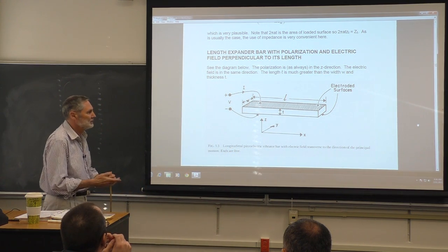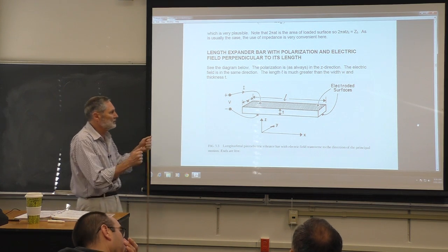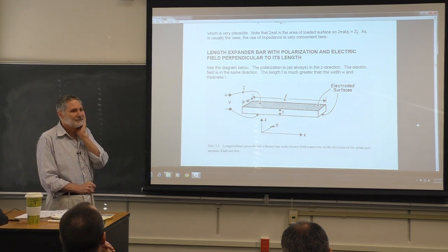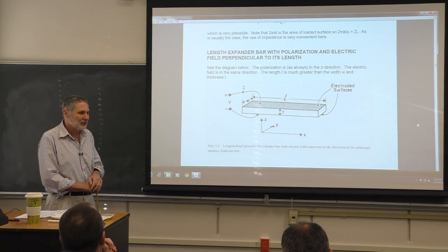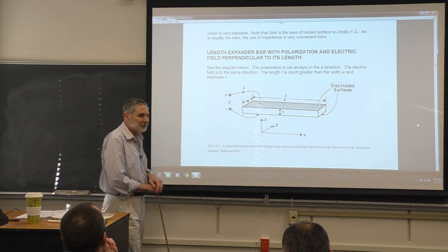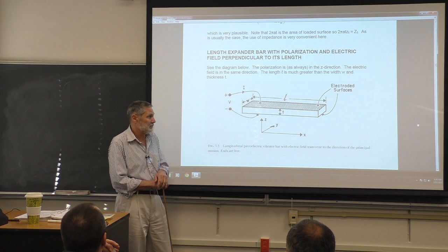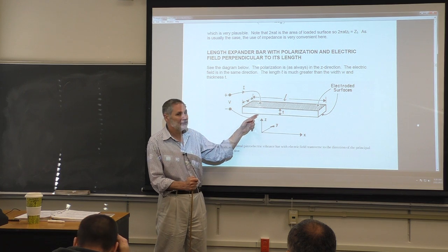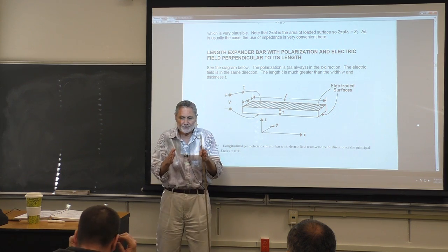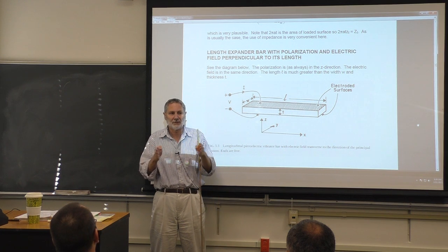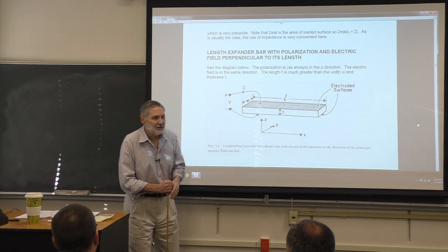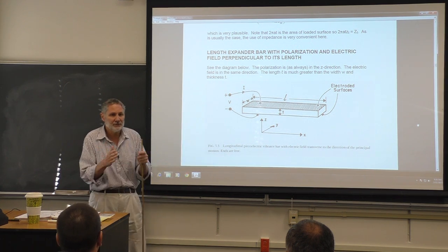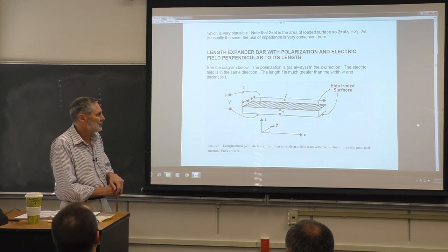So from an elasticity point of view, Young's modulus is what's operating here. We're starting off with that, but what we're going to do differently is this thing that I've talked about before, that we eventually have to confront, and this is our first confrontation. We're not going to assume low frequencies. At low frequencies, the bar will uniformly expand and contract. But as you increase the frequency, eventually you're going to see standing waves in there. With standing waves, you can have nodes and antinodes, so it's not uniform. So we're going to deal with that now. This is our first case of dealing with it.